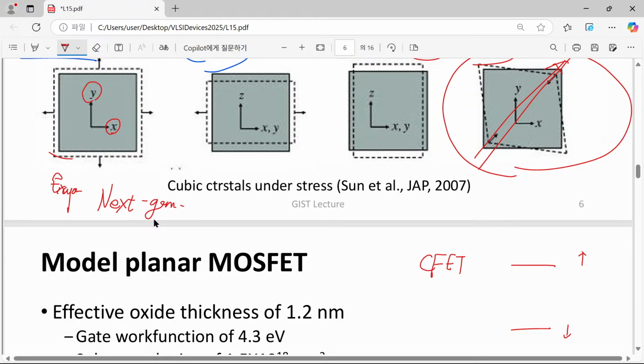So usually what we do currently is fabricate the NMOSFET and fabricate the PMOSFET in the same plane, front side, and just tie them up. So this is the typical case. But in the case of this CFET technology, what we try to do is fabricate a certain FET and introduce another FET on top of this bottom tier one. This is a bottom tier, and there is a top tier, and they have different polarities.